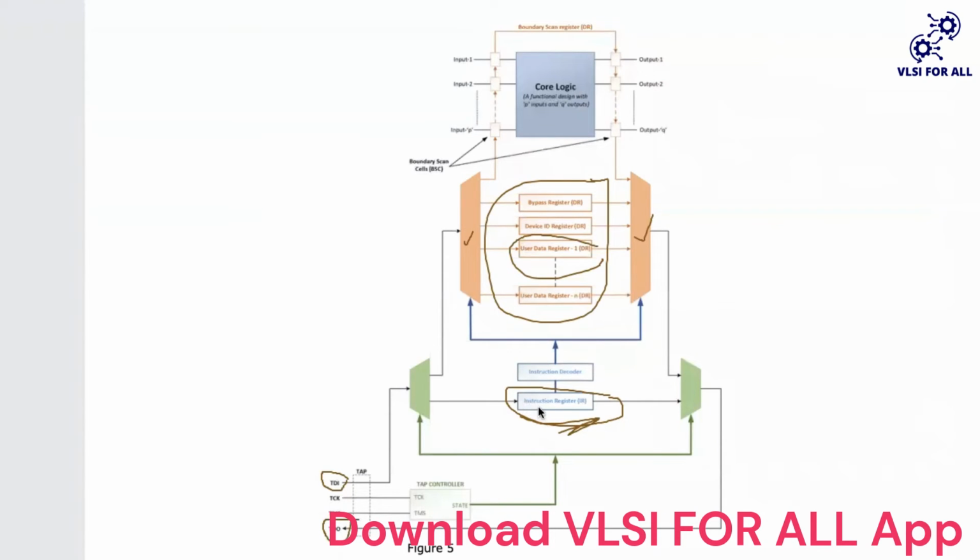Basically, you can read out and program this IR register through this serial interface only. And what we are doing with this control is either programming the data register or the control register, based upon the TAP controller. What we were covering earlier, we will touch more into the TAP controller. But just to explain that IR and DR concept, I was covering this one.